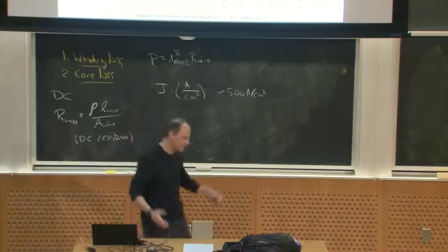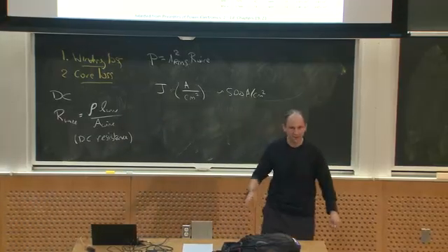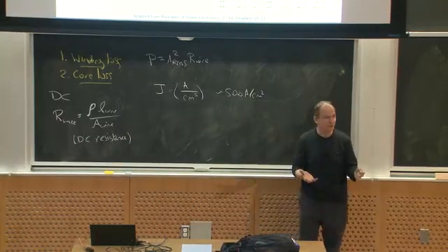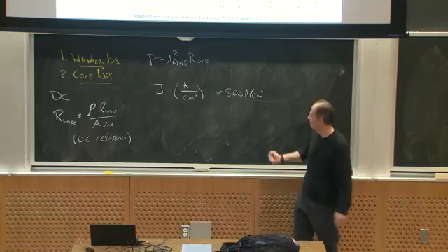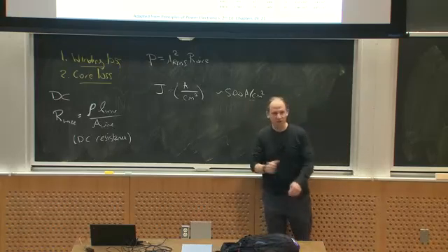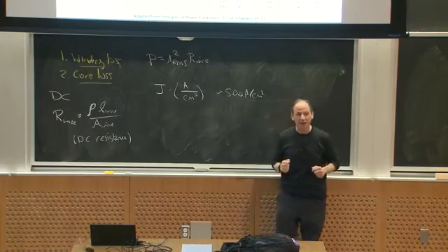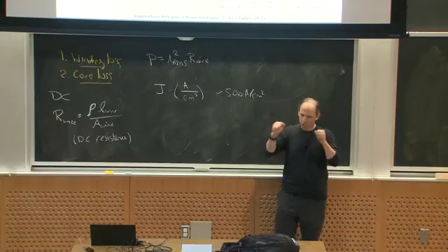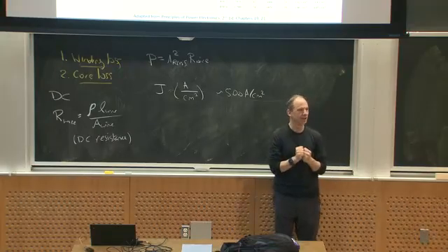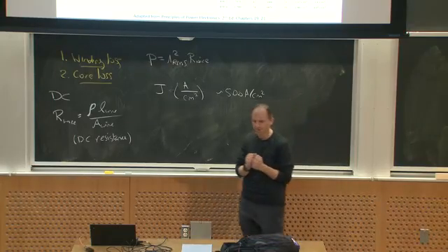So typically you might start your design off and say, if it's big, maybe I'll use 100 or 200 amps per centimeter squared as my guess. If it's smaller, maybe I'll go to 500 amps per centimeter squared or even a little bit higher. And then what's really going to limit me is how hot the thing gets. Okay. Any questions about that?